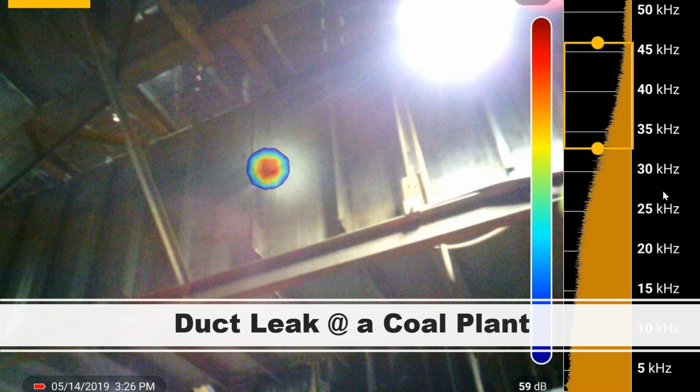Okay, next question. Can you find natural gas leaks at low pressure, for example, 7 inches of water column to 11 inches of water column? So I'm not real good at the water column calculations. I'll tell you that I have detected higher flow air leaks at 4 psi from 10, 20 feet away. Very small air leaks, relatively speaking.